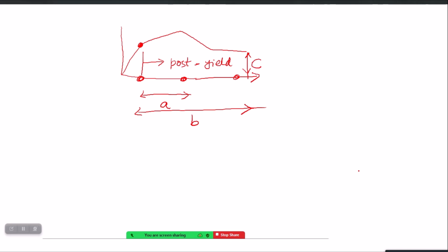And similarly you know that there will be the IO, LS and CP values, and they also will be in the form of deformation. So all the inputs are in the form of deformation, and you are relying on the ductility of your beam in order to get a good performance, right? So this kind of plastic hinge is called ductile type, or deformation controlled.